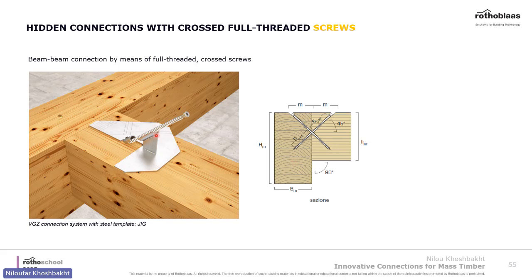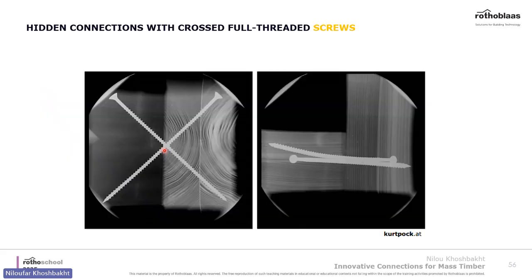And we also provide jigs for 45-degree insertion angles. But please note that even with using jigs, wood sometimes tends to find the path of less resistance. It's possible that a screw can enter crooked, and it's normal for longer screws to have this behavior. So the deviation is okay to some extent, but we don't want it to deviate too much. And even if you use the jig or not, for longer screws, you might have this.